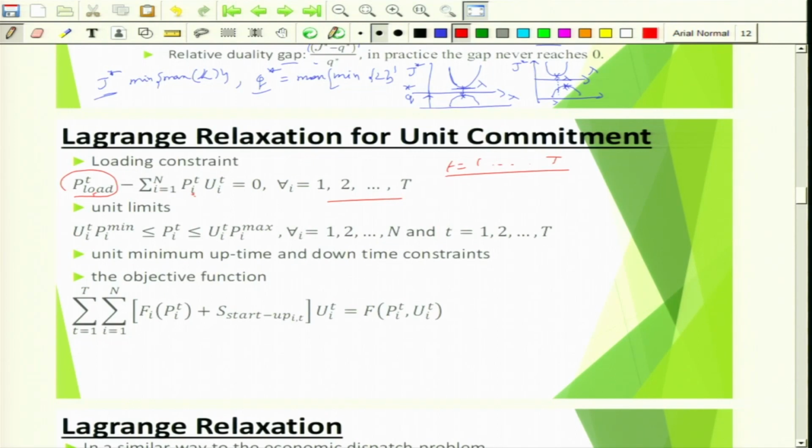Now if you see here, earlier, unit commitment considerations were not there in the constraint. Now you need to add the commitment of the generator, which is either on or 0. That means u_i(t) varies as either 0 or 1. That is multiplied with the generator available for that time, and then the algebraic summation of the load minus the total generation for that specific time interval should be equal to 0.